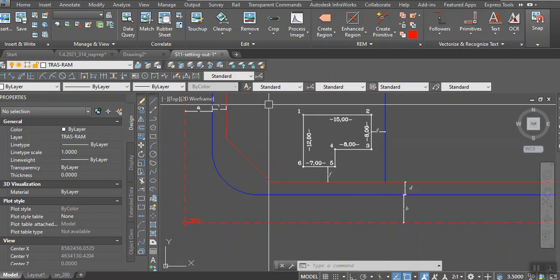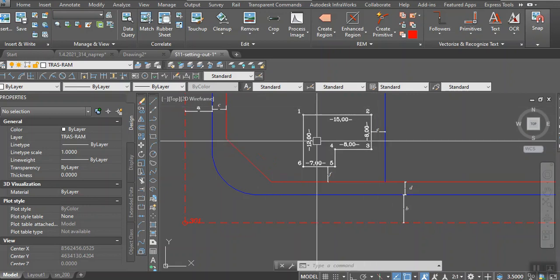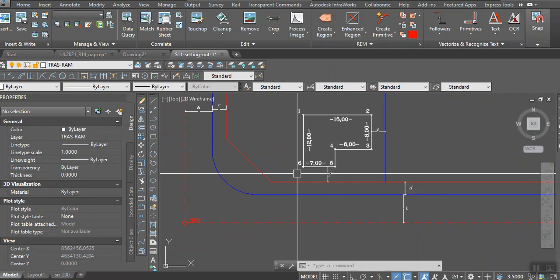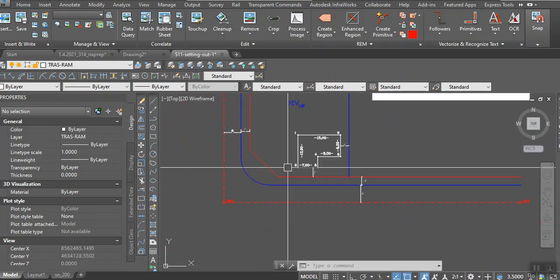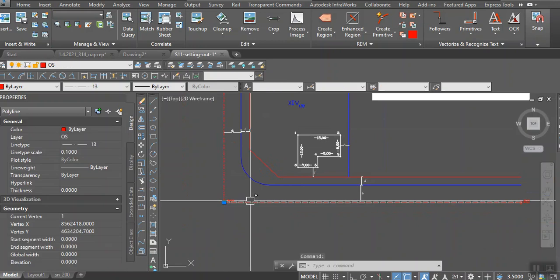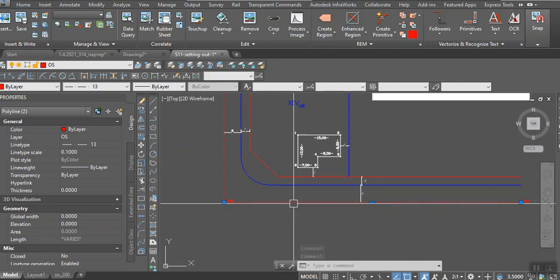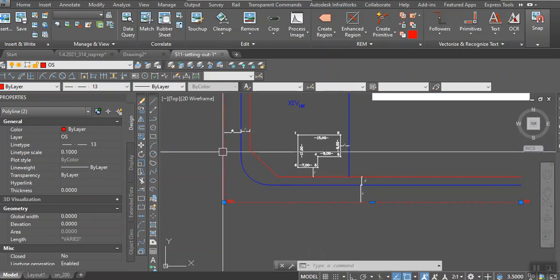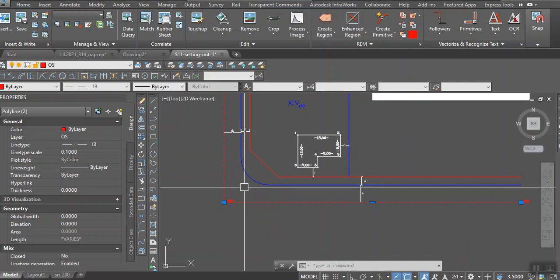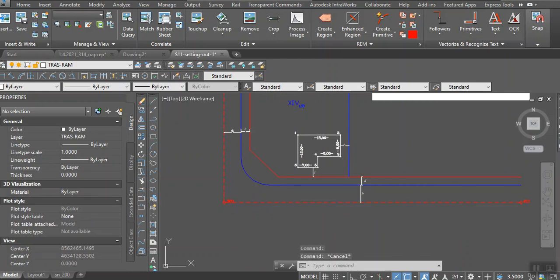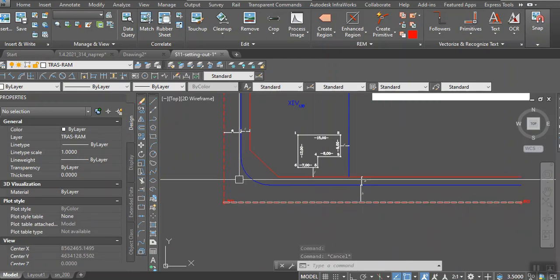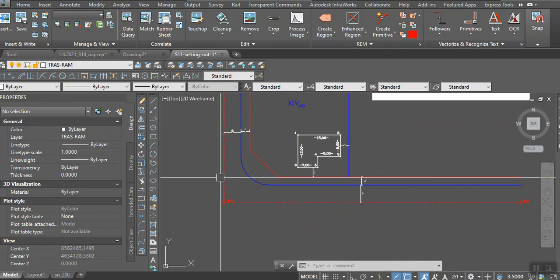Firstly, you need to number the points so that you know which point is which number. After that, you should know that these two lines are absolutely perpendicular, and this one is horizontal and this one is absolutely vertical. They are the same as the coordinate axes of the geodetic coordinate system. So in this direction we have the coordinates y, and in this direction the coordinates x.